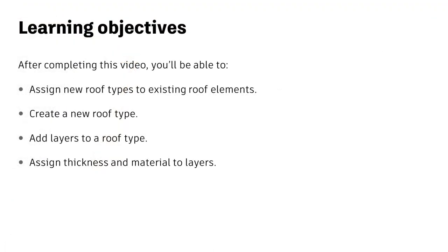In this video, we will see how to create a new roof type and assign it to an existing roof. We'll see how to add layers and adjust their thickness to define a complex roof build-up. And we'll also see how to add materials to those layers.